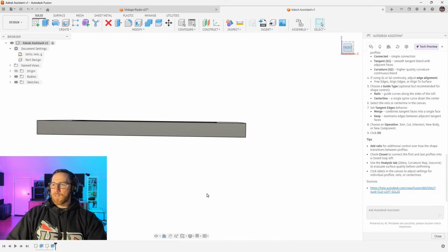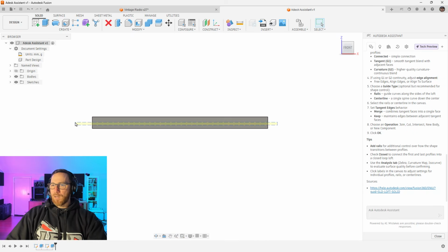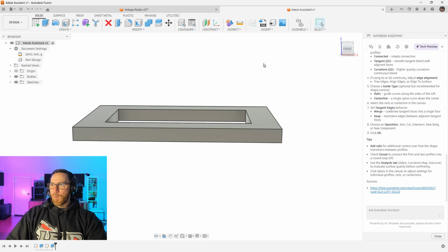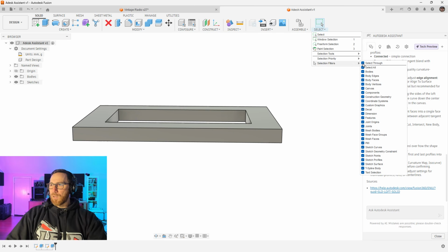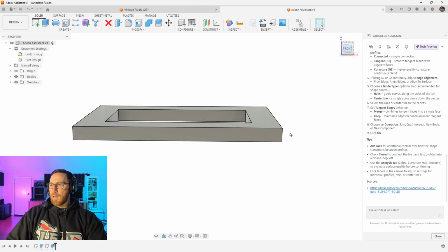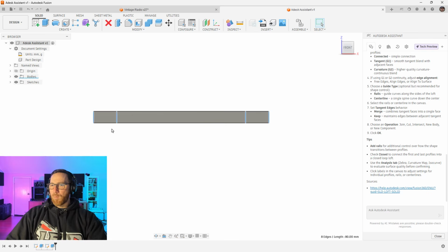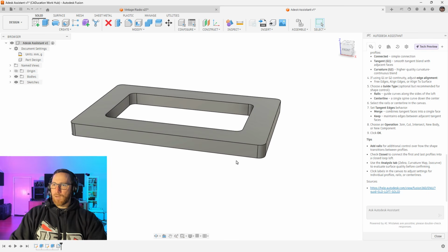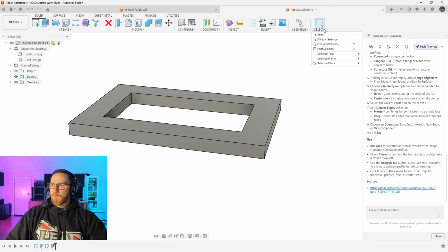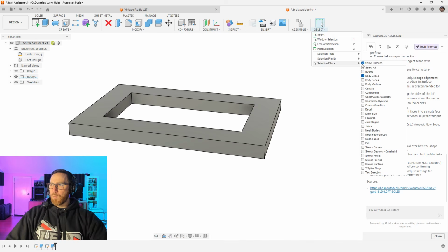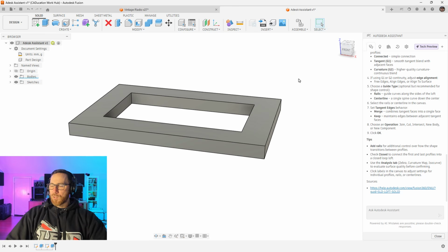The way that we have to do this now is by doing a box drag from bottom right to top left, but we need to do it with our selection manager priority set to edge priority, or turn on the selection filters. So we want select through, but we only want body edges. And then what we can do is box select and grab all the vertical edges, hit fillet, enter 5, and there we go. And so it's possible with a couple of steps, if you know what you're clicking and where to do it. It could be much better if the tool was just improved.